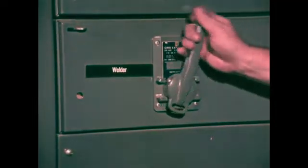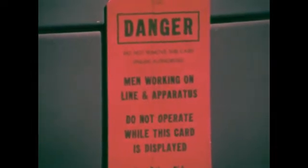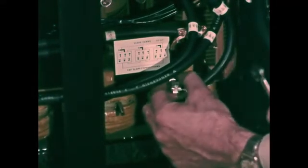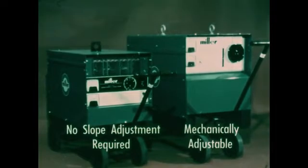It is a simple matter to make new slope connections on the 250 ampere constant voltage power source. The first essential step is to be sure the primary current is turned off. Never work with the interior of any power source until you are sure the primary current is turned off. The taps connected to the reactor coils are clearly identified for slope adjustment. A convenient diagram for making tap connections is provided by this manufacturer. While slope in the power source used in our demonstration is mechanically adjustable, a new generation of machines has slope preset within the machine and no adjustment is required.